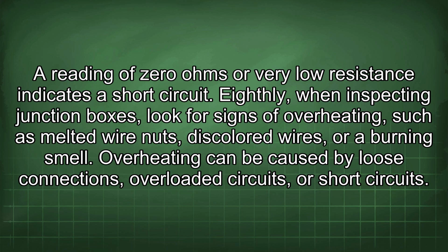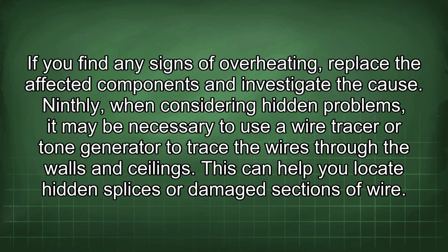Eighthly, when inspecting junction boxes, look for signs of overheating, such as melted wire nuts, discolored wires, or a burning smell. Overheating can be caused by loose connections, overloaded circuits, or short circuits. If you find any signs of overheating, replace the affected components and investigate the cause.